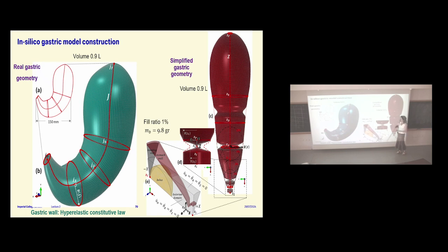So this yellow is, you imagine there's a spherical bolus that lands in your stomach. This is the stomach wall, which will undergo those waves, and it will squish this out. And this gray box is a Eulerian domain, which basically means that you've got your mesh here, which moves independent of your material, such that you can simulate very large deformations. Otherwise, your mesh will get distorted if you use pure Lagrangian, and you're not going to get any results from here. So in the beginning, we just did it as a solid in an empty stomach, which of course is not very realistic.